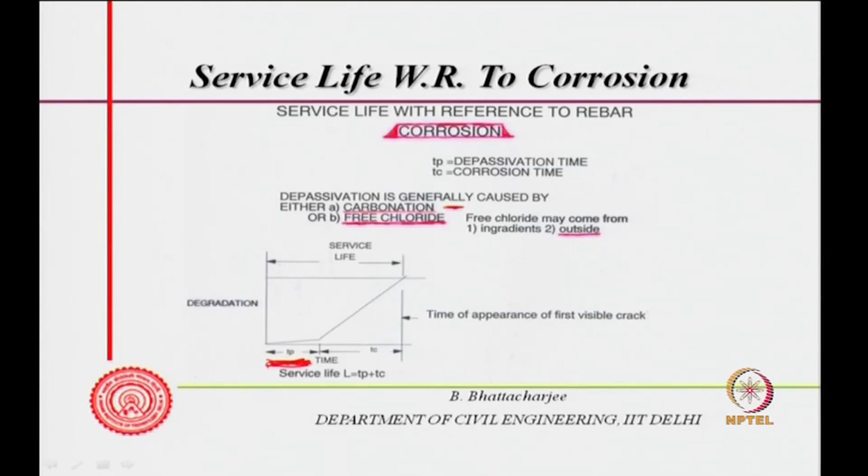We also mentioned last class that at high pH values, the oxide passivates the steel, in other words forms a layer over the steel bar, which does not impair the performance of the reinforcement bar, and in fact, it protects it, and that is a passivation layer.